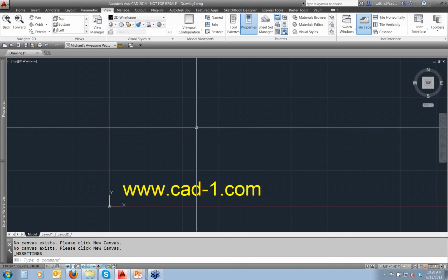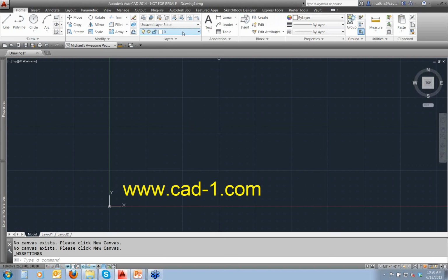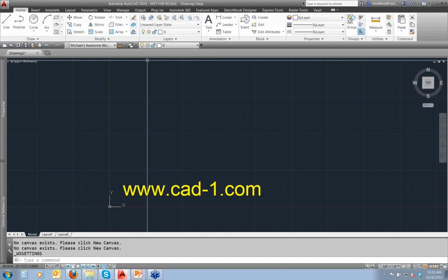All right, and one last question here. Quick access toolbar: I add my current layer, current line type, current dimension style, but I can't seem to find a way to add current color or current text style. So what you're saying is you're adding your layer drop down. I forgot to point that out. I've seen a few users who've done that, and that's a great use of the quick access toolbar to add your layer.